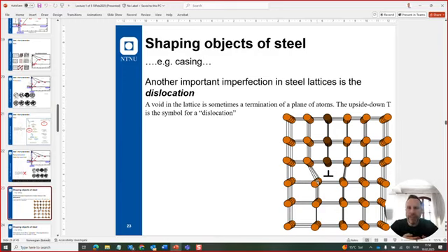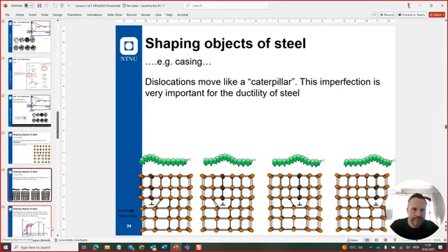Thinking about the stress-strain curve of steel, how it works. Putting a physical shear force sideways on a piece of steel makes these bonds jump. So the bonds that were on the right side now jumped over to the dislocation, meaning that the plane that was before coherent is now no longer coherent, and the dislocation is on a different plane.